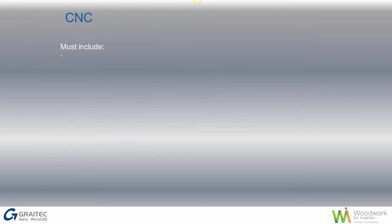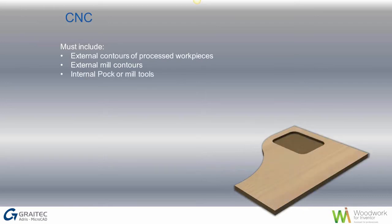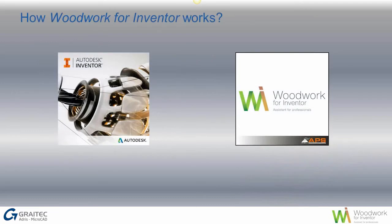You can also put CNC information in, so you can put external contours of processed workpieces, external mill contours. They've got what they call the POC or mill tools. You've got drill diameters and center positions, and you can do this in accordance with grain direction, edge banding thickness, and you can also pick a base point to go from. So one of the questions that often gets asked is, how does Woodwork for Inventor work? Well, Woodwork for Inventor is an add-on to Inventor, so it's not a separate package.